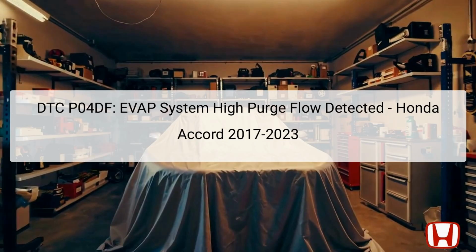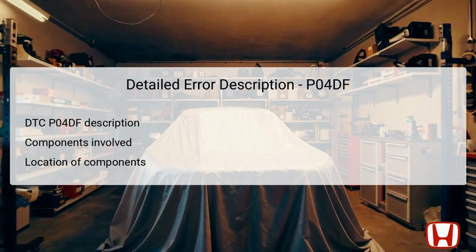To effectively address this issue, it is important to use the appropriate diagnostic tools, such as the vacuum pump gauge and vacuum pressure gauge. Ensure that preliminary steps, such as verifying other possible DTCs, are complete before beginning the specific troubleshooting for P04DF. The DTC P04DF indicates that there is a high purge flow detected in the EVAP system, which affects its ability to manage fuel vapors effectively.